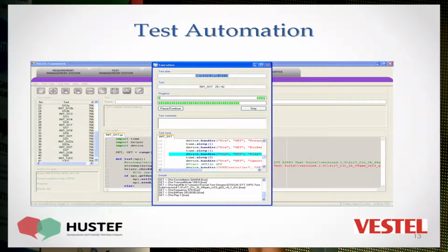We have some reference pictures from before, and we are putting televisions on the test automation system, opening the backside of the televisions, and connecting an LVDS cable to the panel. We are getting captures from the panel itself, not from the webcam, because getting captures with a webcam is not good enough. It's so different. So we are getting the captures with the LVDS cable, and we are comparing the captures by using algorithms like PSNR or OCR.